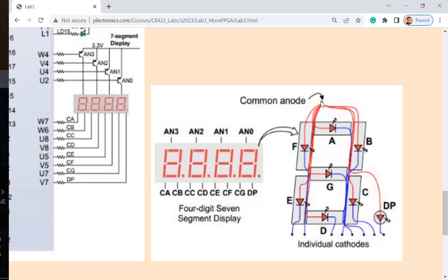If I turn on this one, what would I want to assign to this? 0. So I got a current flow to it. So it's on. And if you give 5 volts here, this is not on, right? Yeah. So you still control it. So this is called common anode configuration. Sometimes you'll see different modules by different manufacturers that have a common cathode. Right? Just ground it here.